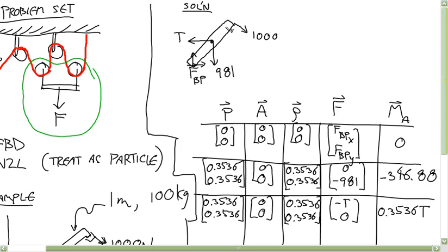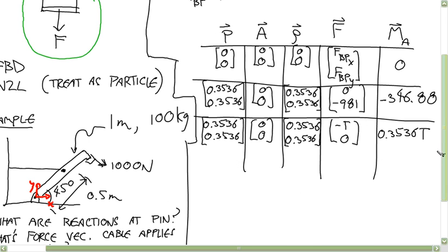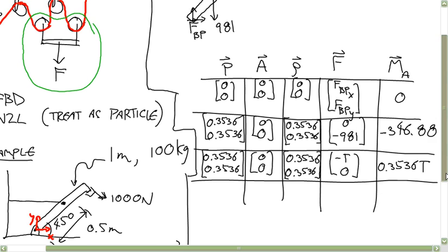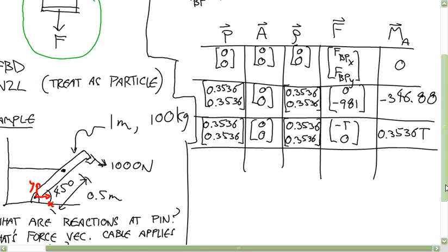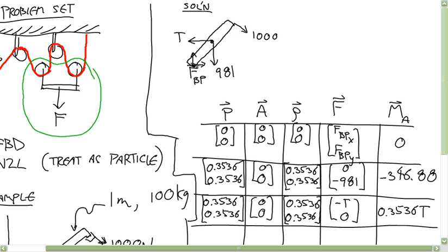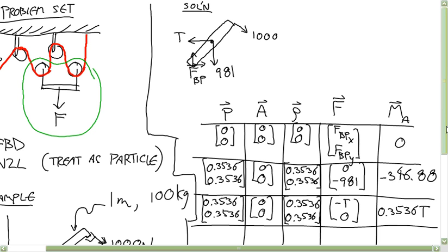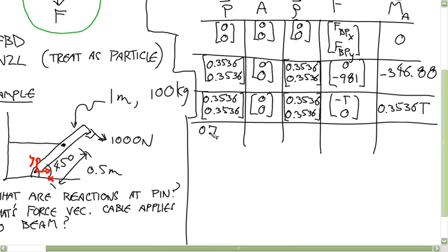And then the last force is this one. Calculating that moment is pretty simple if you think of this as just a perpendicular distance from the force, but I'm still going to fill this out. You'll get the same thing. We know we should get a moment about this point of 1,000 times 1 meter clockwise, so negative. This force acts at 0.7071, 0.7071.